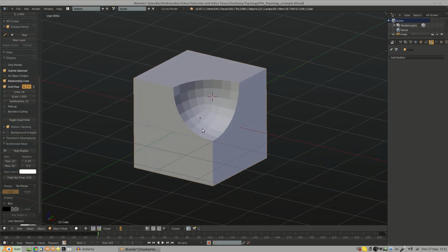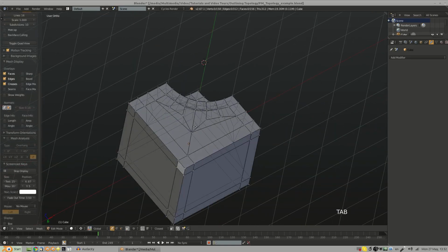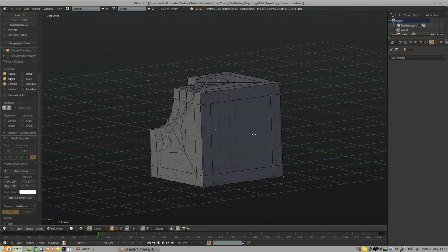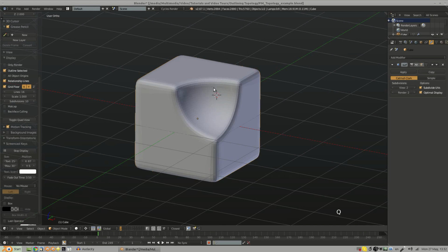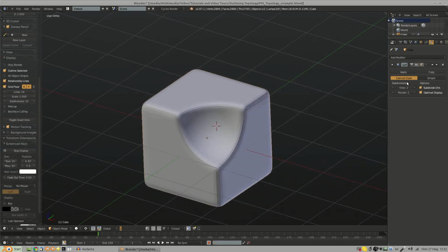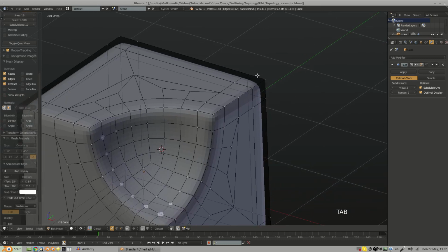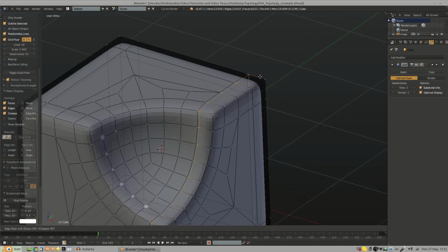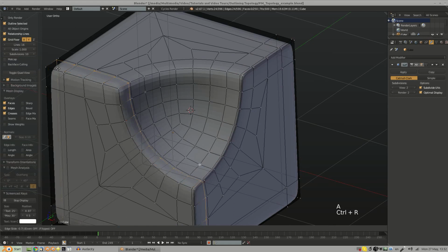So yeah, as I was saying, this is basically our finished shape, and we've managed to keep all these faces nice and simple. And the great thing about this is if we now add a subsurf modifier with Jonathan Williamson's awesome add-on, we can now go in and add our sharpening edge loops. So let's say I put one in there, put it say 0.7, just to make sure these are all equal.